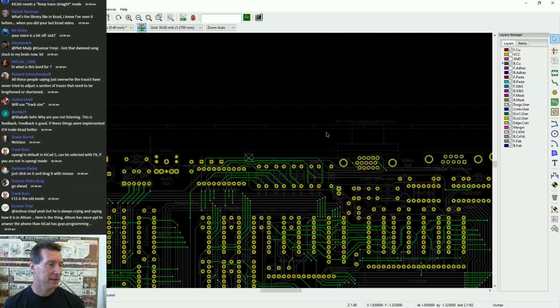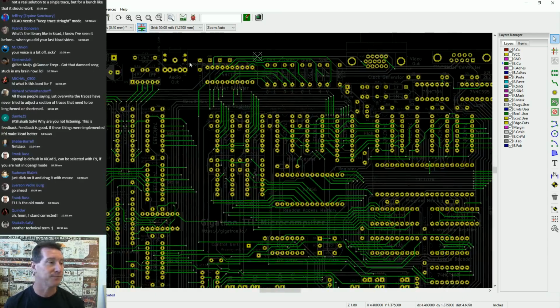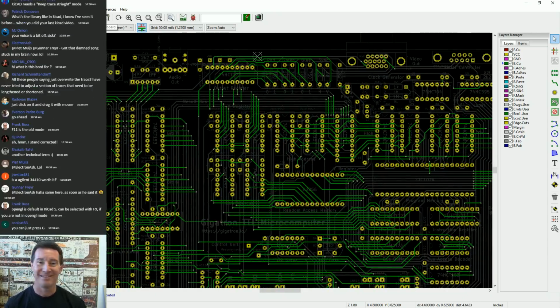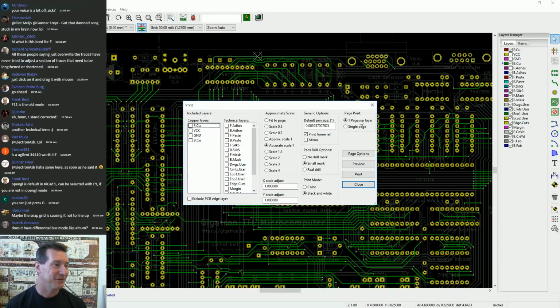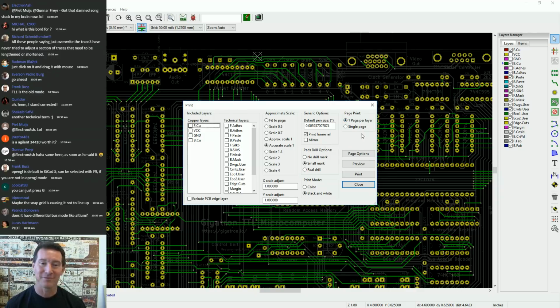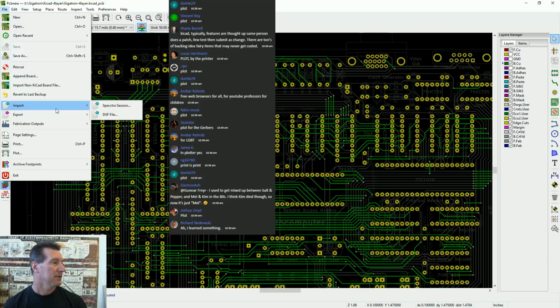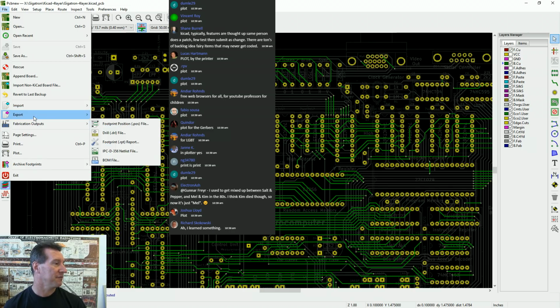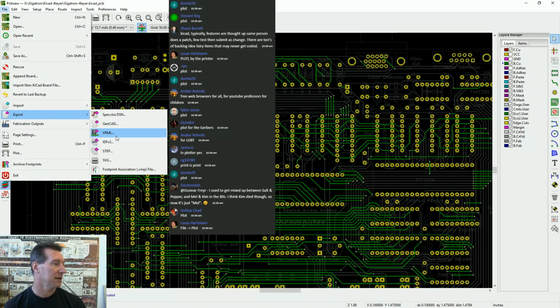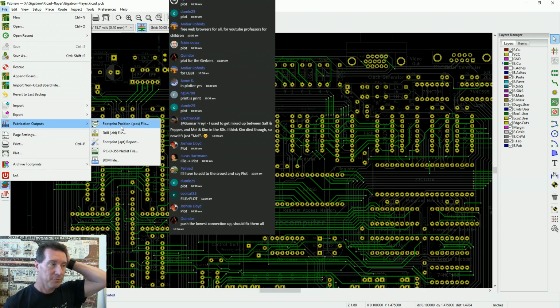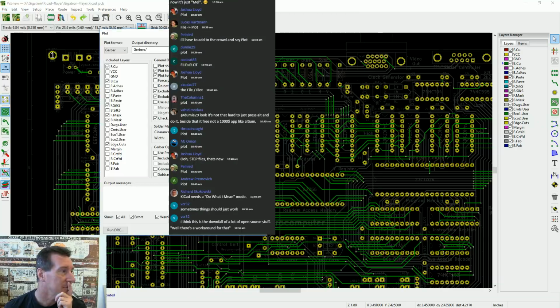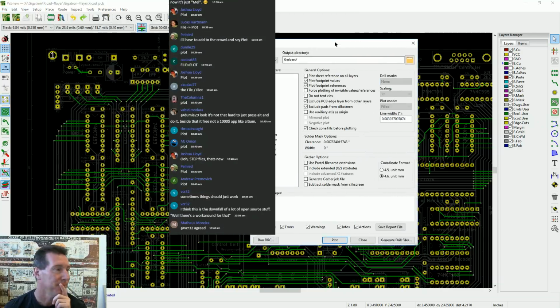Right, so okay, how do we generate gerbers? Sure, there's probably a print board. Is that it? Print? Is print gerbers? Or is print generic options? It looks like paper print. Can you PDF? So I can import Spectra and DXF. Can export Spectra, GenCAD, VRML, and STEP. Fabrication outputs: footprint position, drill file, footprint, netlist file, a BOM. Plot. Output. Gerbers. There you go.